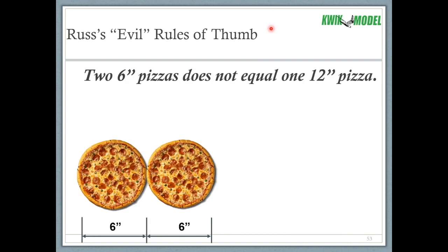Here's another one of my rules of thumb, and this one you can live by. I actually ran into this one time. I had done a design on a two-story house, and I had a 12-inch trunk running from the attic down to the first floor. On the plans, I called out very clearly that I needed a 12-inch clear chase because I needed to run a 12-inch duct straight down, and 12-inch clear means no obstructions.